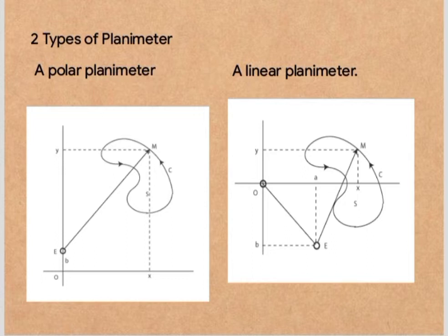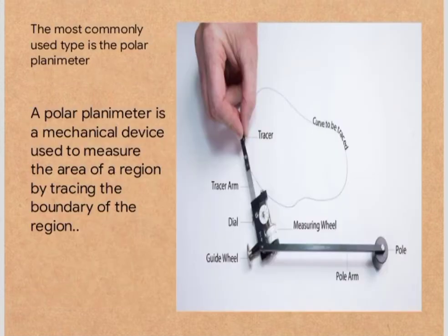While in the polar planimeter, the end opposite the tracer point is restricted to move along a circle, from the word circumferential. This is done by making that point, which is the hinge between the tracer arm and a secondary arm, one end of which, the pole, is fixed.